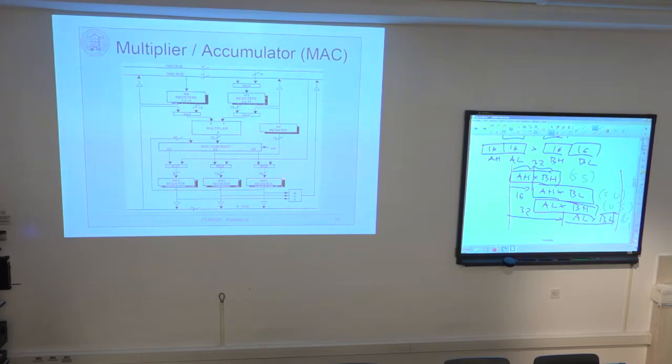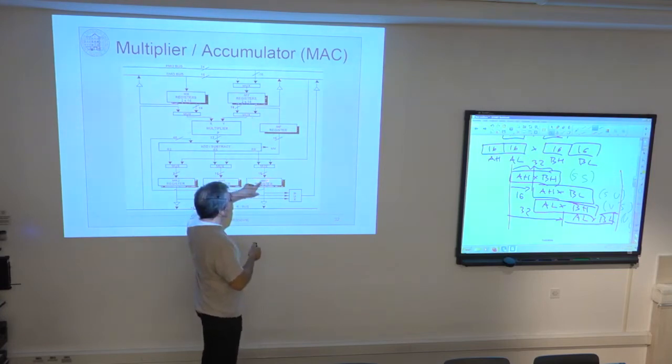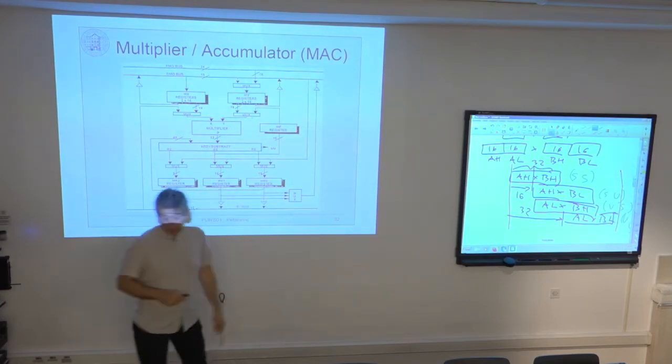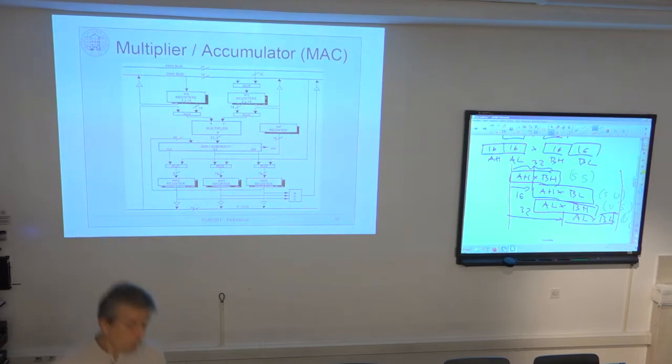And finally, if I want to store the result in the memory, since this is 40 bits wide, I must select one of the three at a given time. So, for example, I use this mux and say, okay, write MR0 to memory, so emit the value to the data memory data bus, and then write these values to some address in data memory. Then in the next instruction, I take MR1, write it to the memory, and so on. Because the data width is only 16-bit, okay?